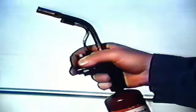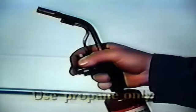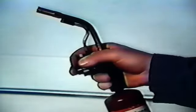As you may remember from an earlier tape, we suggest the manifold be slightly warm to facilitate the removal of the O2 sensor without damaging it. To make this test, you'll need a digital high-impedance volt-o-meter and a clean-burning propane torch. It's important that you use only propane to prevent damage to the sensor. Starting with a cool sensor, heat it with the torch and watch the meter.